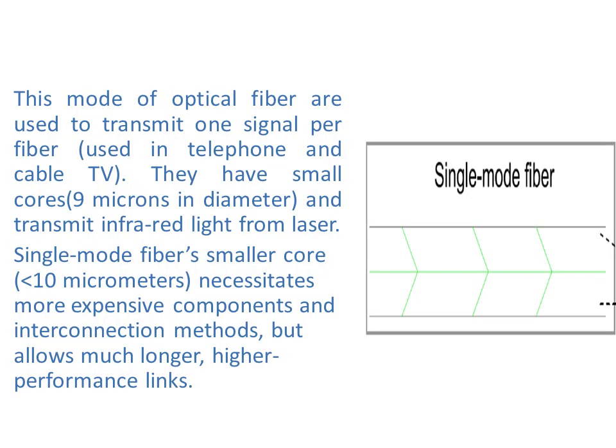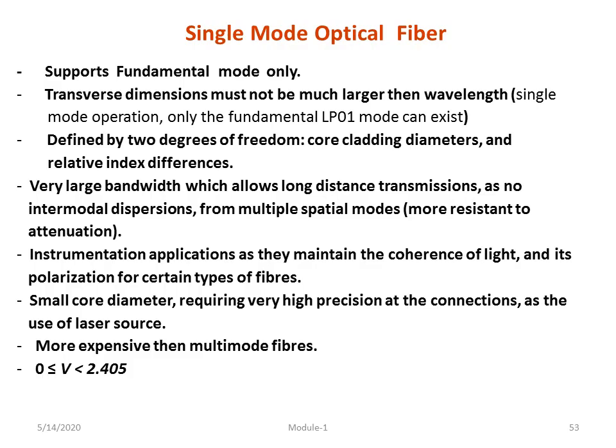There's a difference between the different design parameters we need to consider for the single mode fiber. One design parameter is a small core diameter, around 8 to 10 micrometers, and it requires very high precision at the connection, as a laser source is used.